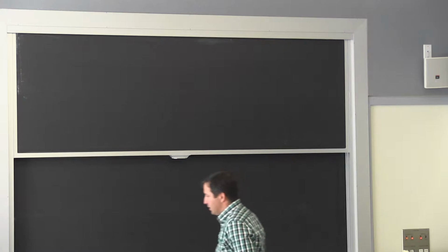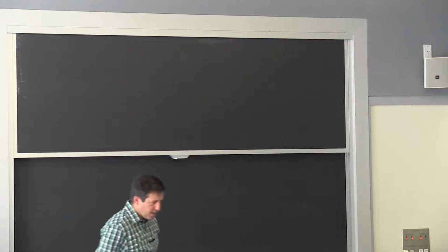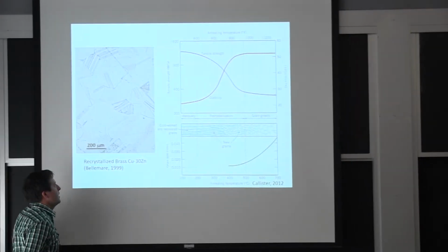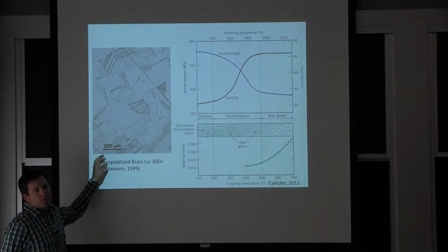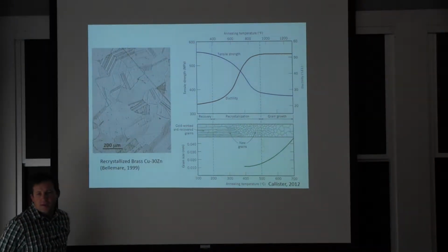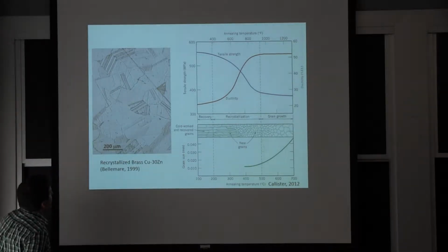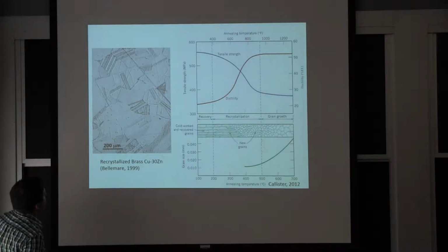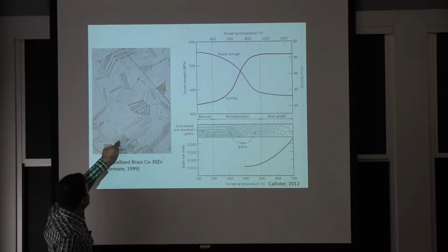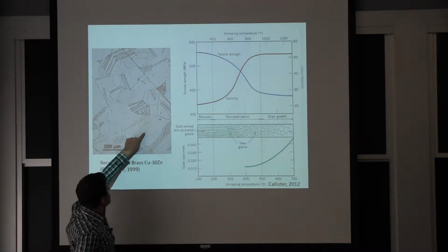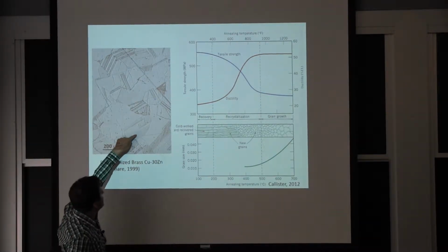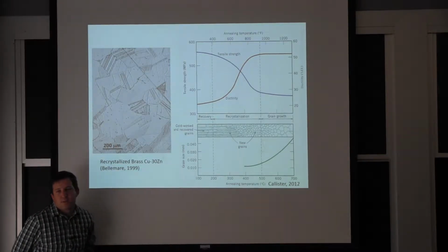And what is very important in any forming operation is what happens to the microstructure. In the end, you'd like grain. So I'm just showing a grain here that's different from yesterday. This is actually a cross-section of the brass sample I passed around yesterday. And I don't want to make it look more complicated than it is, but the grain is this entire area, and what you see in it are just twin boundaries.